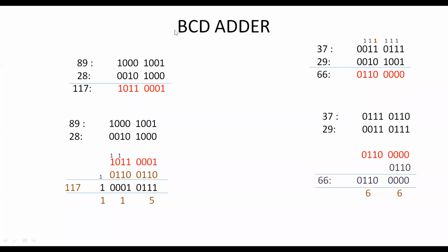1 plus 1, we are getting a carry. Here we are generating a carry. Here I am writing the carry as 1. This is the carry that is generated as an intermediate carry. Where did this carry come from? When adding the first 4 bits, I am getting a carry from the third bit to the fourth. This is A0, A1, A2, A3. When adding A3 and B3, we are getting a carry that is generated to A4.